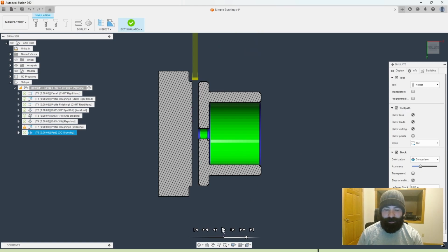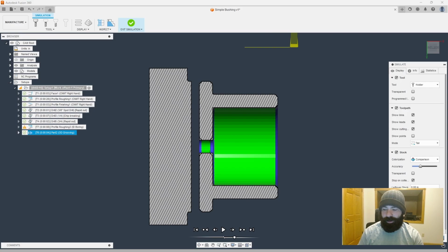Let's go ahead and restart that operation. We'll hit play this time. It'll be a little easier on all of us. So there's our actual tool path coming in. There we go, speed it up just a hair. We did that first little peck, and then we came in and chased that actual chamfer profile, putting that backside chamfer on our part when we parted it off.